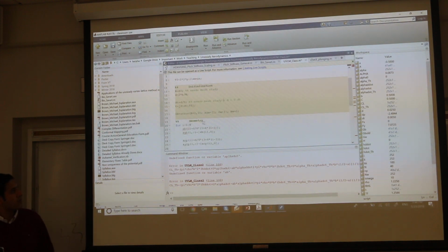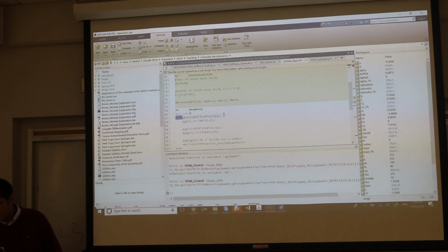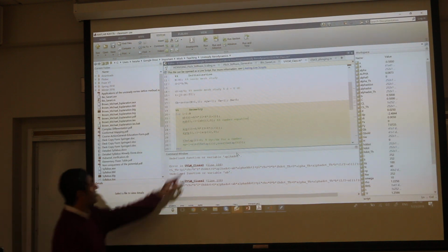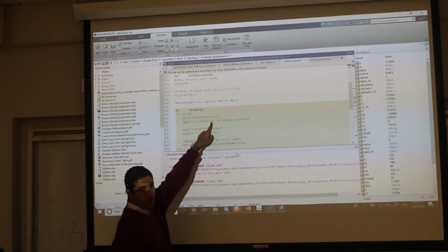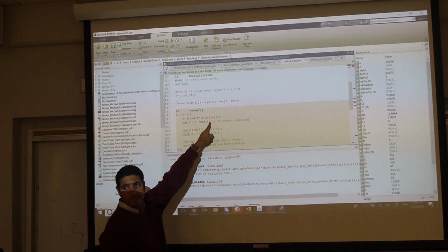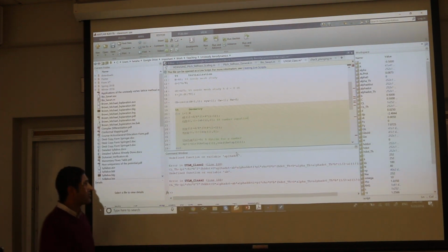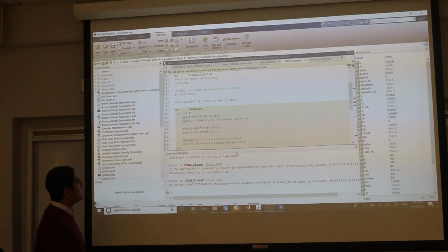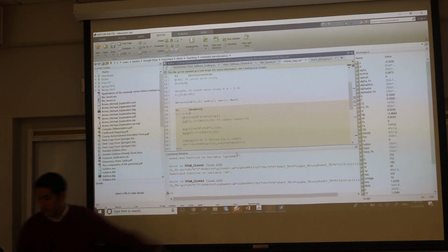And then we go to the geometry. So we defined our x bound and y bound is 0 because it's a flat plate. So I'll write here for you. Here you can put your camber equation, right? If you have a camber equation, the y is not 0 anymore. Just put whatever equation is a function of this x, right? So if you have yc as a function of x, you put it here as a function of this x, right? And the same for the x, y control points.